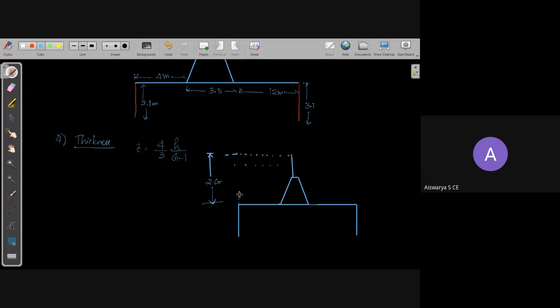First of all, at this section where we have provided the cutoff wall, there will be a certain drop which can be represented as a vertical drop. Okay, then what will happen? Here there is no vertical cutoff wall just below the weir. At this weir portion, we have not provided any kind of cutoff walls. So there won't be any vertical hydraulic loss at this portion. Okay, so I can show the hydraulic gradient line as an inclined line up to my downstream end.